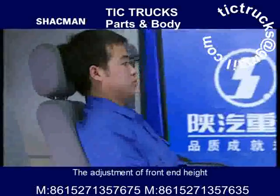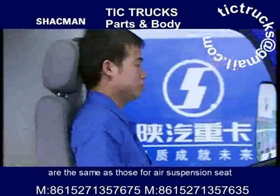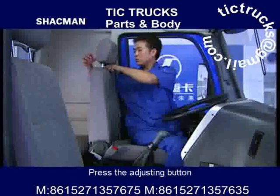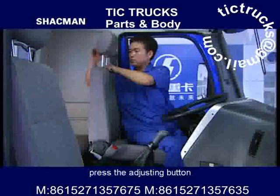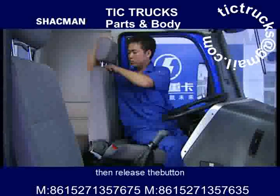The adjustment of front end height, rear end height, and backrest angle are the same as those for air suspension seat. Adjustment of headrest height. Press the adjusting button. Pull up the headrest to the desired position. Press the adjusting button. Push down the headrest to the desired position, then release the button.